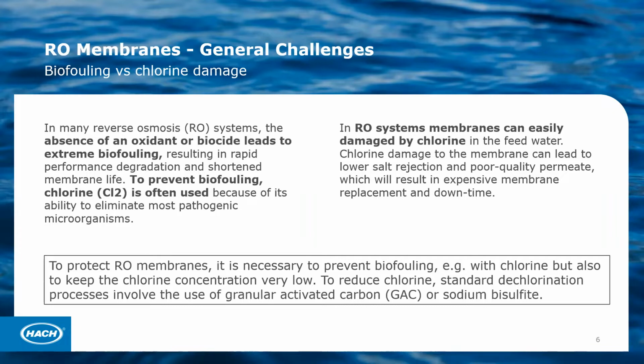And that is also a potential problem, leads to reduced pass-through of our membranes, leads to maintenance requirements, and is something that we need to be mindful of. It can eventually destroy our membranes, if not at least cause us a hassle in terms of shutting down our RO skid, or whatever form your reverse osmosis membranes exist in your facilities. They may need to be taken down for maintenance or possibly replacement.